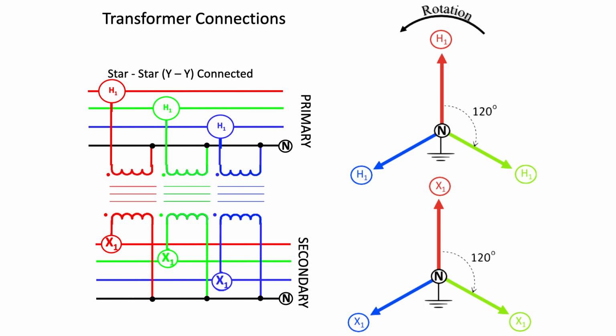Another solution to the problem of third harmonics is to provide a path for them using a set of tertiary windings connected in delta that allows for these circulating currents to flow. The provision of an extra set of windings increases the cost of the transformer considerably, which may be offset, of course, by using them to supply power to an extra load such as station service.